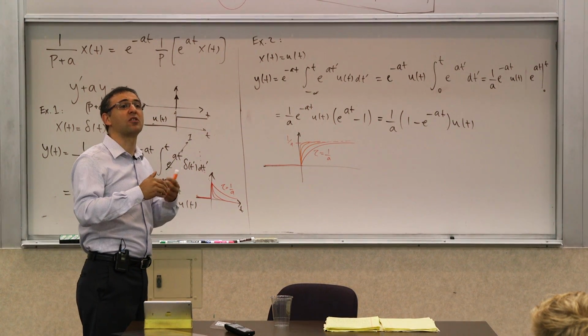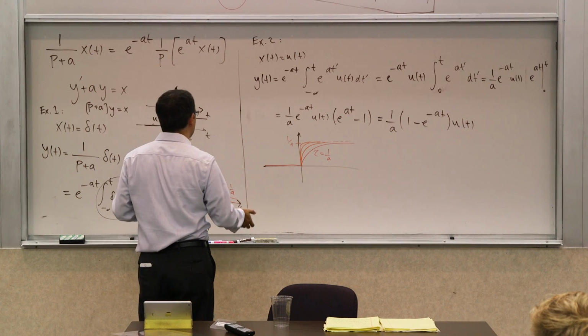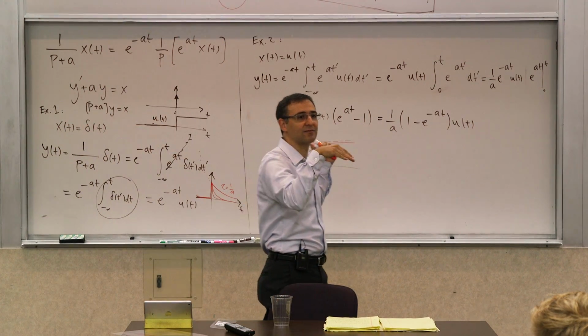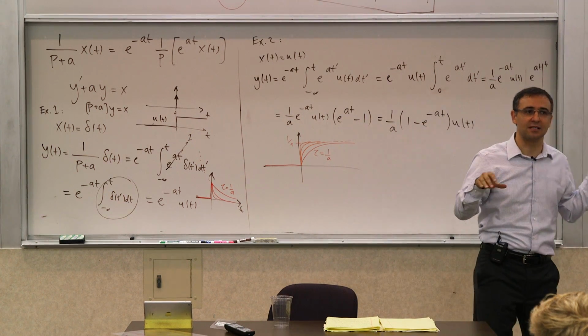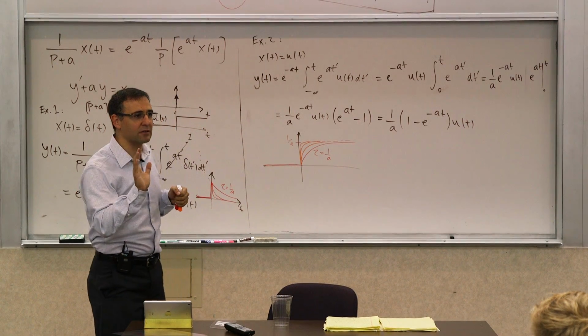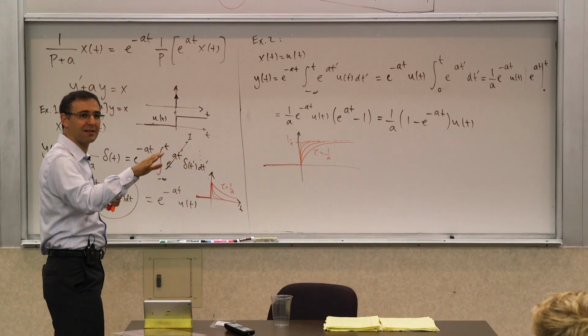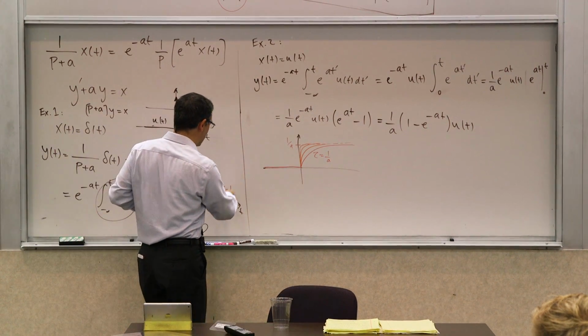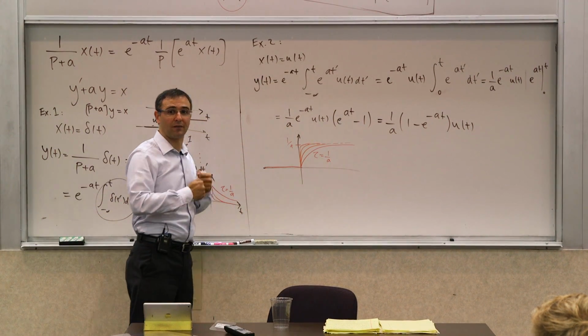That's the cutoff frequency or bandwidth of a filter. So this is essentially the simplest filter you can make. It's a low pass filter. It passes lower frequencies, again, roughly speaking right now, and it blocks the high frequencies or attenuates them at least. You should have a sense for frequency, right? These sudden jumps are things that are high frequency, right?